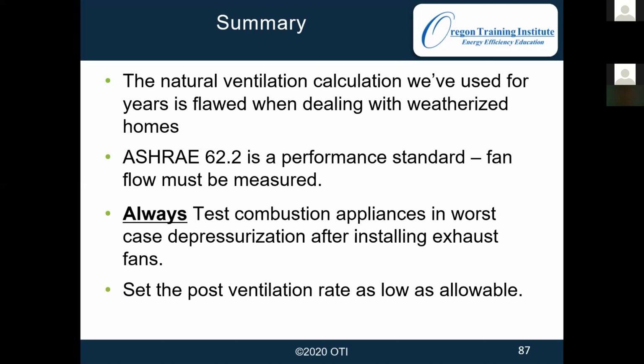And remember, as we air seal the house, make it more airtight, and we put in these exhaust fans, that's going to create a depressurization effect on the house where the pressure is going to get lower and lower. And if we have combustion appliances, sometimes that can interfere with their operation. So we want to be sure and thoroughly test out at the end of the project to make sure we are not creating any health and safety issues.